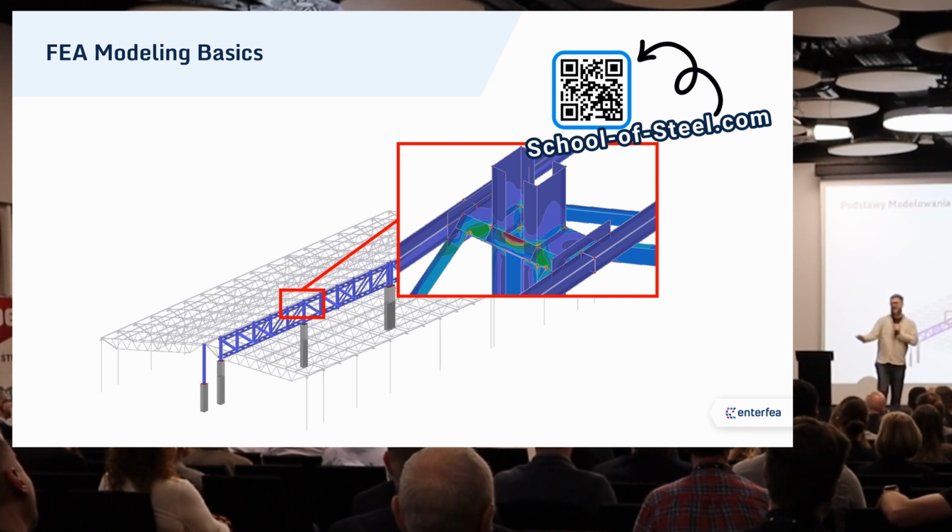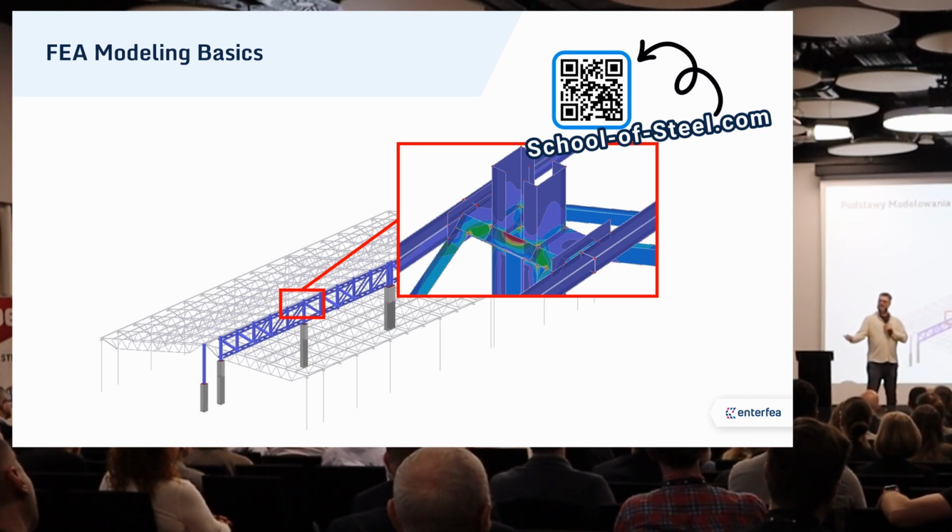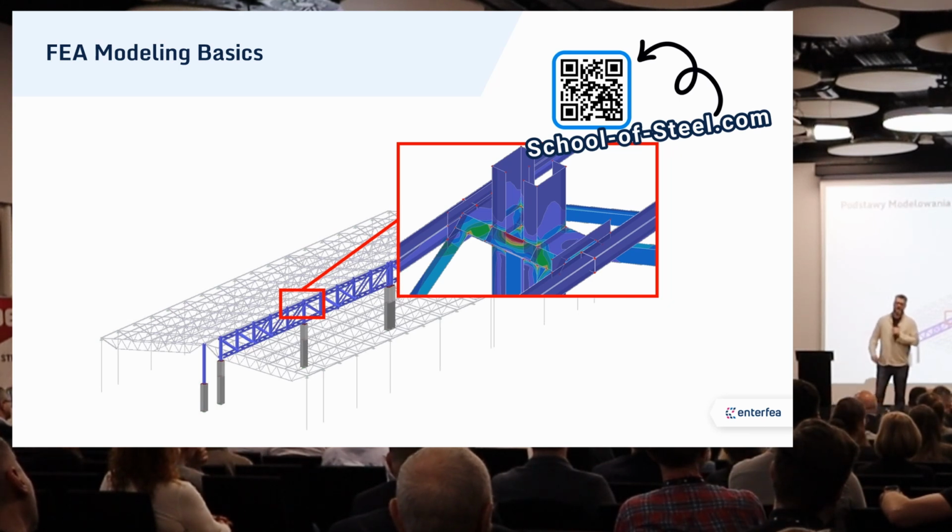Then, of course, your model floats in air because you don't have the rest of the structure in it. So the best solution would be to simply support one of the beams as a rigid support, and then use the loads from your static model, the forces in each member, as active loads on each other beam.